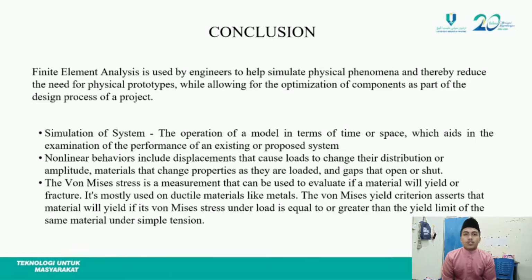Nonlinear behaviors include displacements that cause loads to change their distribution or amplitude, materials that change properties as they are loaded, and gaps that open or shut. The third point is that the von Mises stress is a measurement that can be used to evaluate if a material will yield or fracture. It's mostly used on ductile materials.